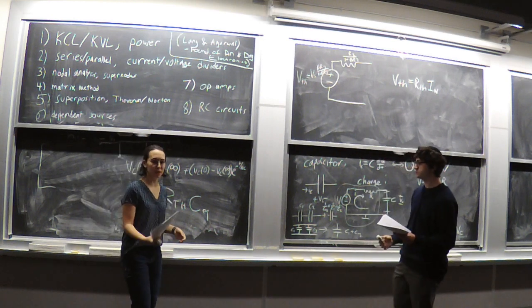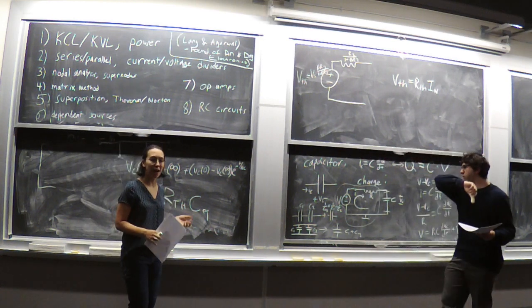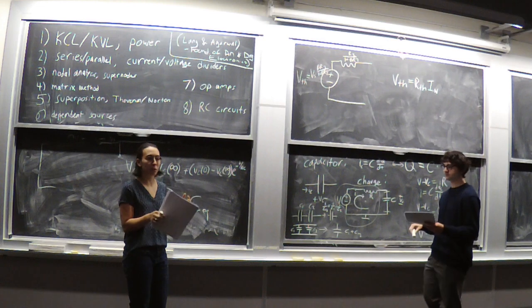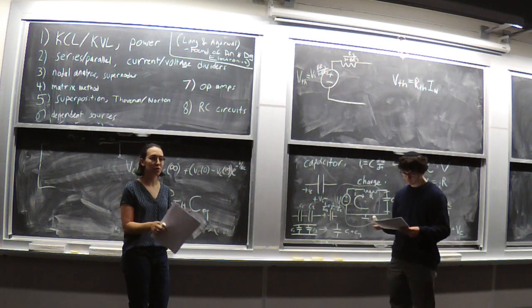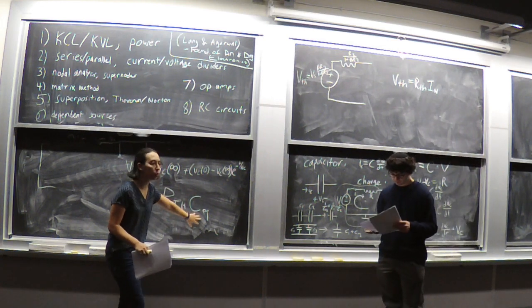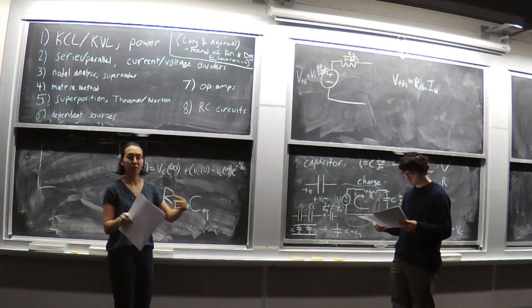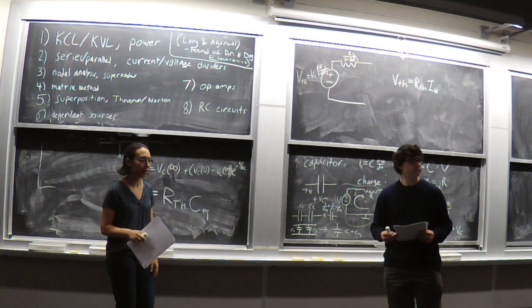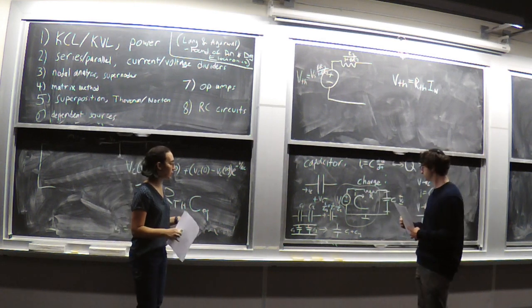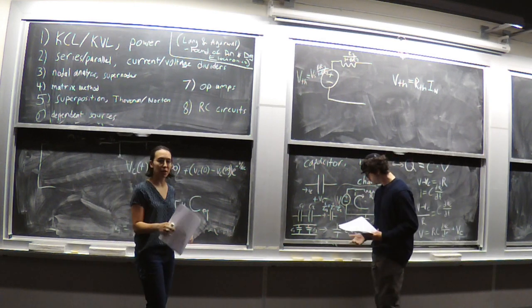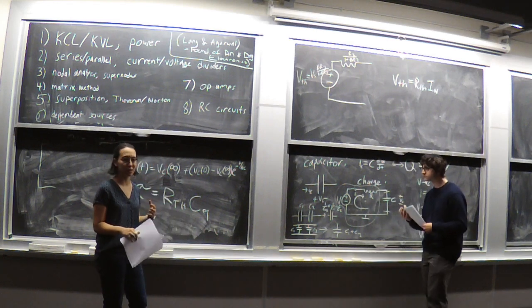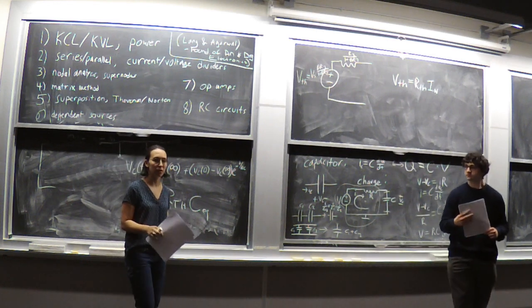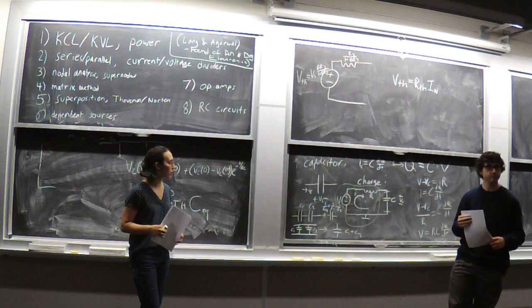So you did something similar to that on lab 5, where there were those two capacitors, you wanted to turn that into some equivalent capacitor network, and then you simplified the left-hand side of that circuit, and you turned it into some Thevenin equivalent circuit. And so when you're thinking about the initial voltages and the final voltages, you would be reducing that to what is the initial Thevenin voltage, what is the final Thevenin voltage, and that sort of thing.